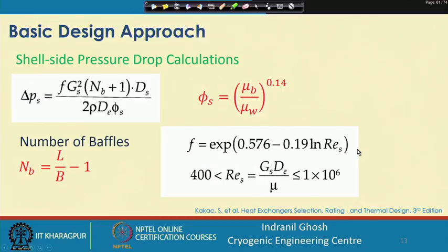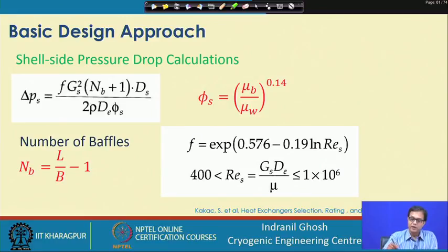So, now if we are able to get all this information, we have some rough calculation of the shell and the tube, and now we have to rectify it, or rather we have to go for the rating problem. As you can understand, we have done a rough estimation of the heat exchanger. Now, we have to apply the Kern method, where we have been told about the heat transfer coefficients, and the pressure drop correlations have already been given.